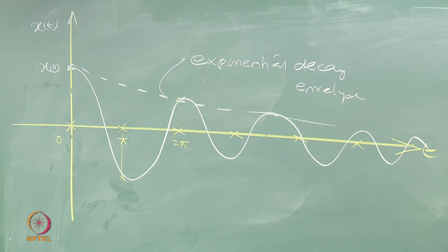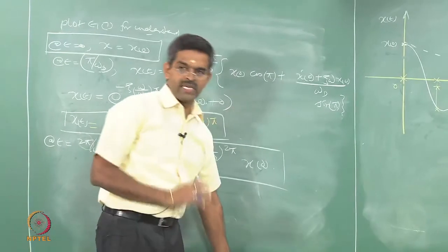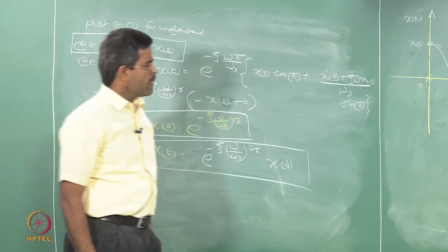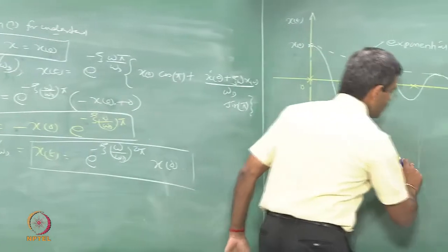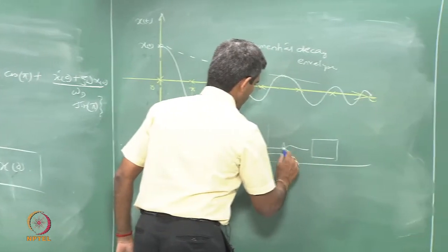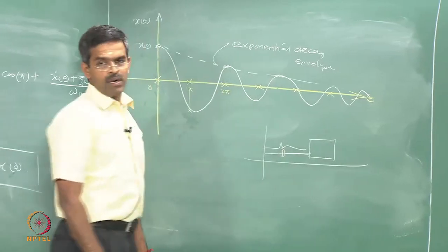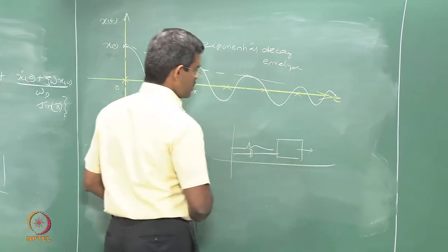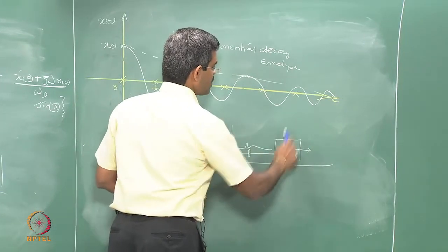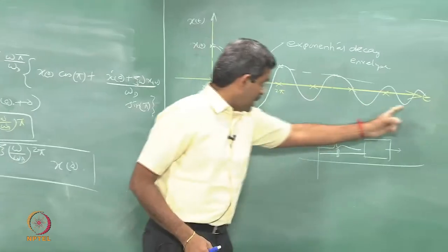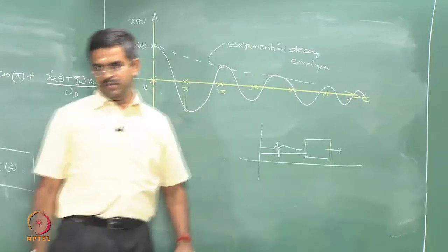Now, one can ask me a question interestingly, how to estimate zeta from this. Now, take a spring mass system, with or without a dashpot, set a vibration to this, will come to 0, plot an accelerometer or a displacement transducer, try to capture this decrease in response experimentally.